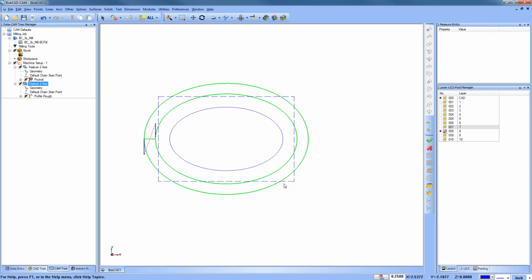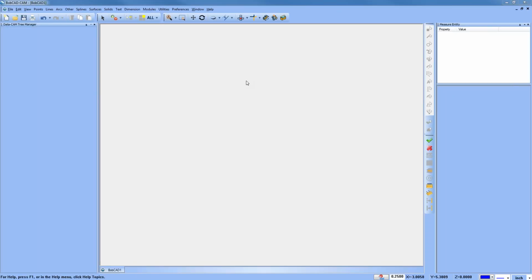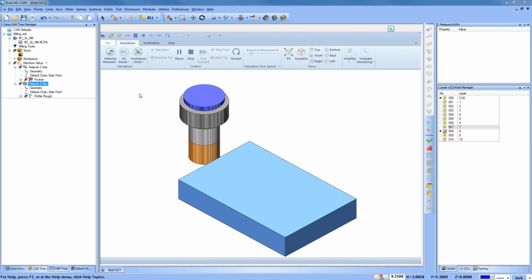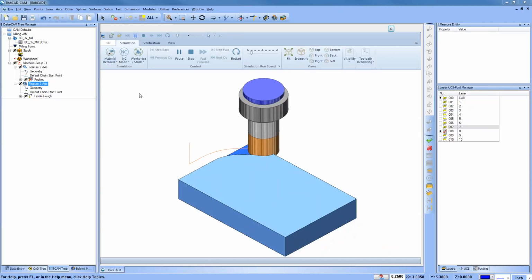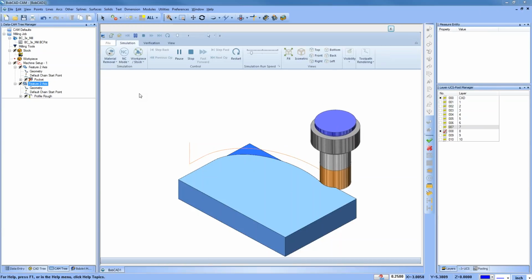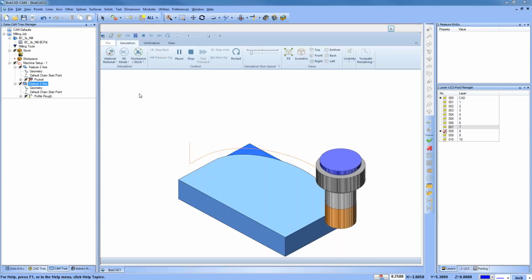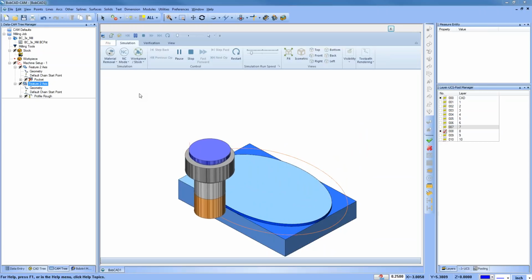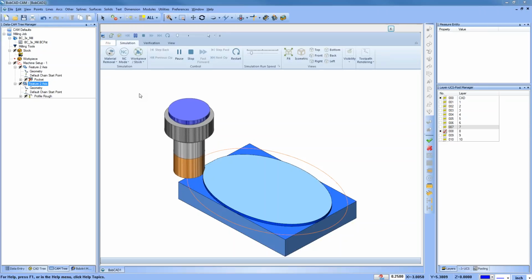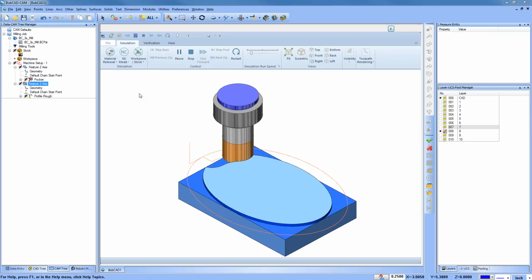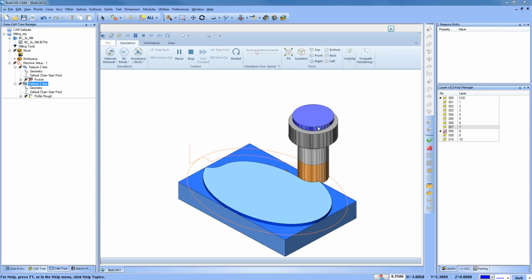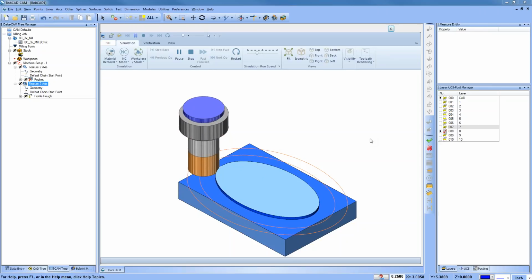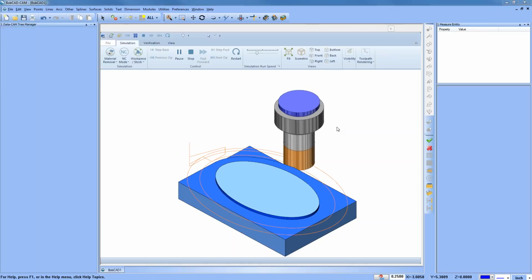You may use side roughing to clear a boss down as such. So instead of a pocket, you may use a larger tool to clear material around the boss. Again, this isn't always the most efficient way because you're not targeting all the material like you would in an advanced pocket. But what's useful about this is you get very consistent tool paths. So it cuts, offsets, works its way in, cuts, etc. And it's very consistent. You're going to get a consistent result. So this is another example of where you can use side roughing in order to work your way into the part. Okay, all right, so let's stop that one for a second.